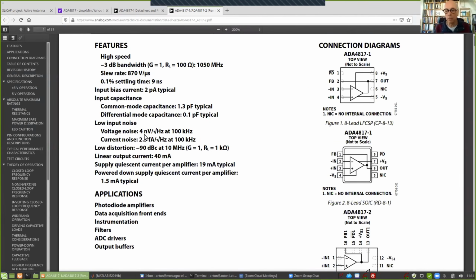Four nanovolts per square root of hertz and not 3, but you cannot get lower. You can get 3, but that is not a unity gain stable operational amplifier, and it will be hell to get it stable, and it is very high frequency. So we see basically we had for this antenna length a showstopper for the noise, because we cannot find a controller like this.